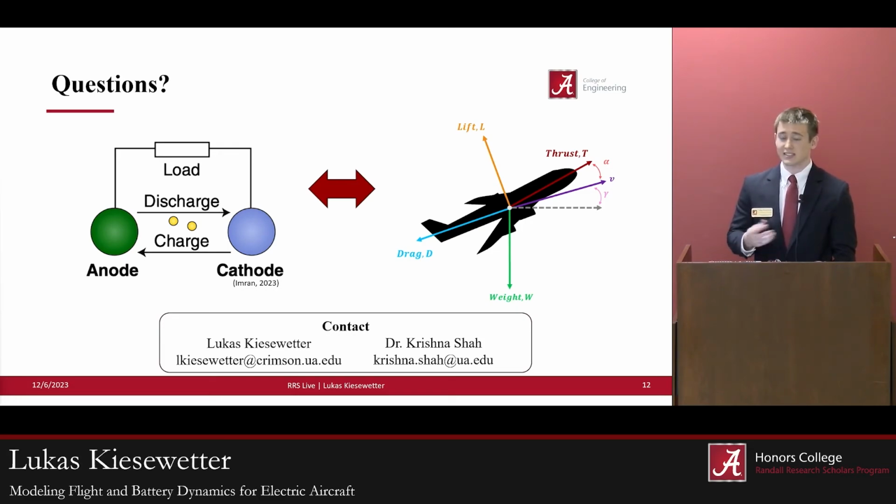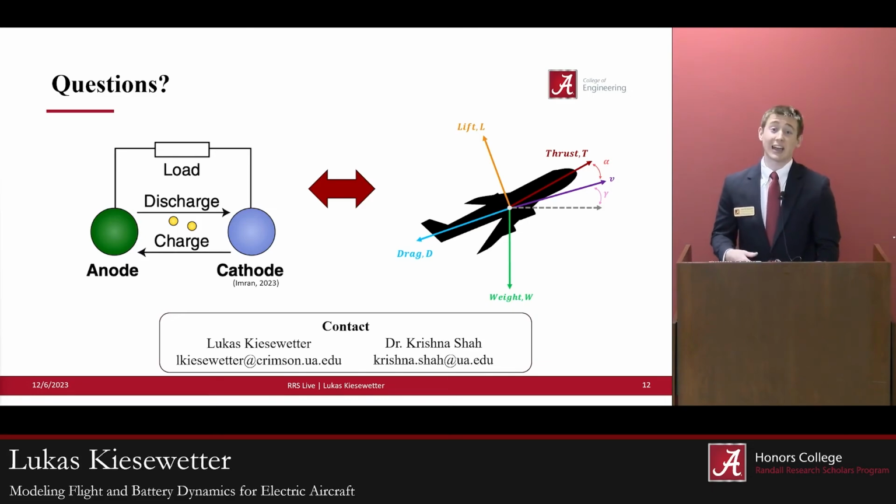So that's the benefit, but when we're wanting to project the performance of the aircraft, we want to be as accurate as possible, because then this will lead to better planning on the logistics side of things and aircraft design. So the pseudo two-dimensional model can handle the electrolyte solution between. The single particle model does not look at the electrolyte at all. And so there's certain physical behaviors that happen with the pseudo two-dimensional model that couldn't happen in the single particle model. So just getting more accuracy to ensure the safety of these flights would be really big.